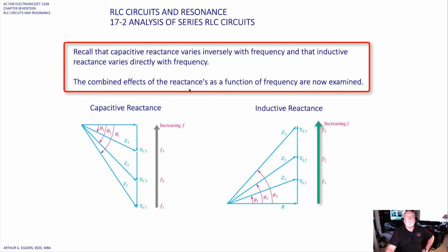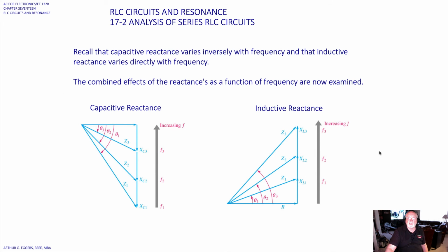So the combined effects of the reactances as a function of frequency, as we've seen before: you can see that in the case of the capacitive reactance, we're in this negative moving angle. In the inductive reactance, we have this positive moving angle as we increase the frequency.